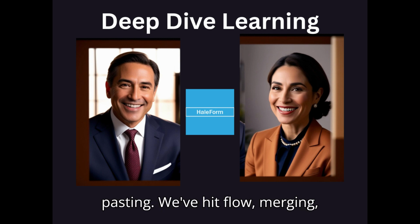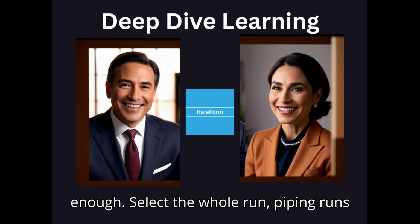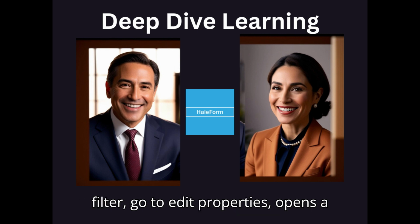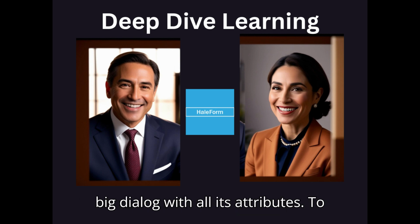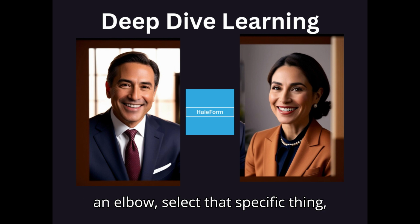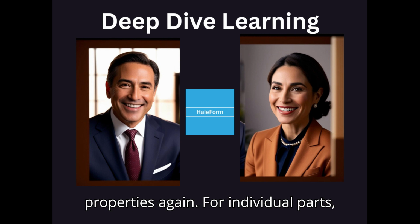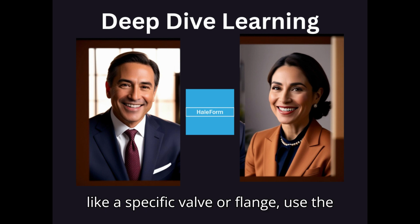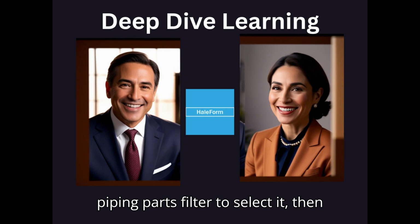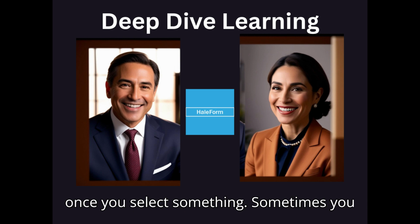We've hit flow, merging, copying. What about just editing properties of a run or its bits? Easy enough. Select the whole run. Piping Runs filter. Go to Edit Properties. Opens a big dialog with all its attributes. To edit just a branch or a straight piece or an elbow, select that specific thing, Piping Features filter, then Edit Properties again. For individual parts, like a specific valve or flange, use the Piping Parts filter to select it, then access its properties. Often there's a quick Properties panel on the ribbon, too, once you select something.